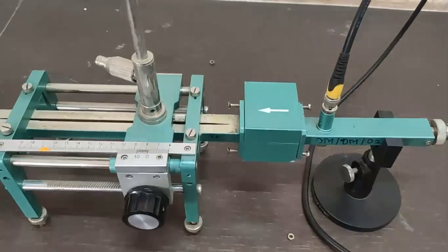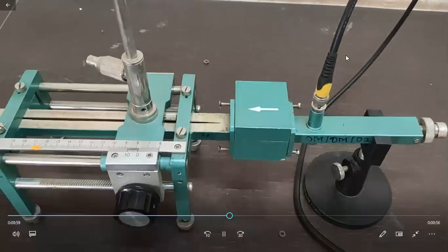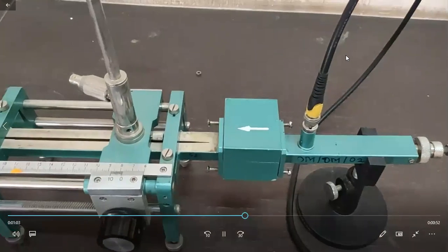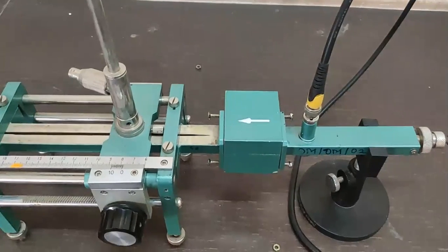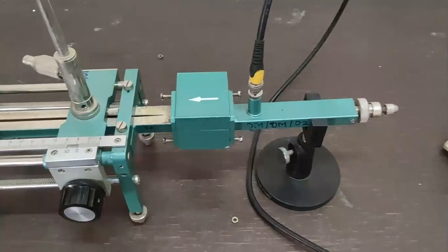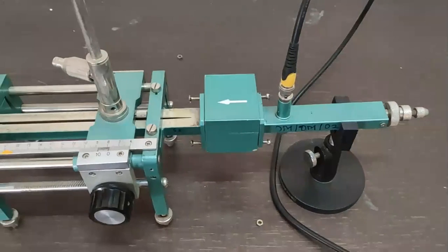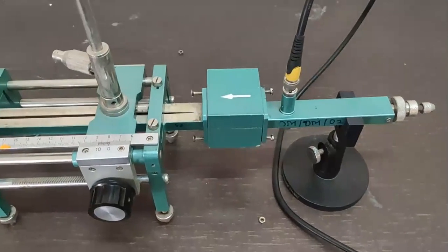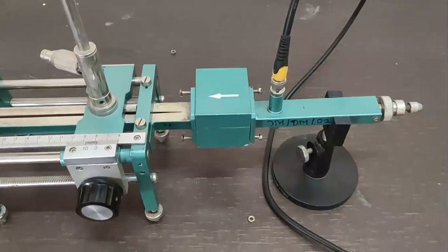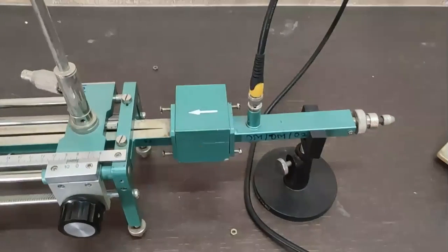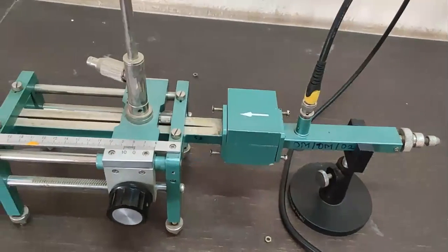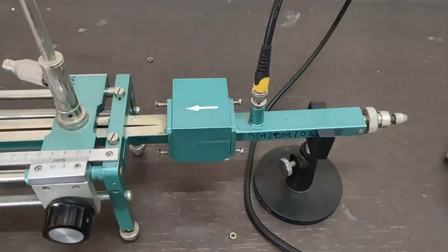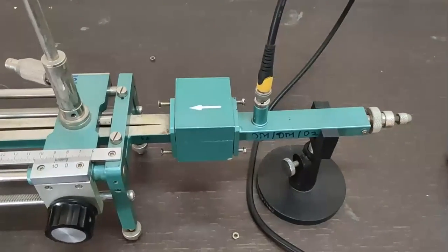So isolation is equal to 20 log to the base 10 of V12 upon V21. V12 means port 1 is connected to the slotted section and port number 2 is connected to the detector mount, whereas V21 is in reverse order, meaning port number 2 is connected to the slotted section and port number 1 is connected to the detector mount. In this way you can calculate insertion loss, isolation and VSWR for this particular experiment, that is the isolator.